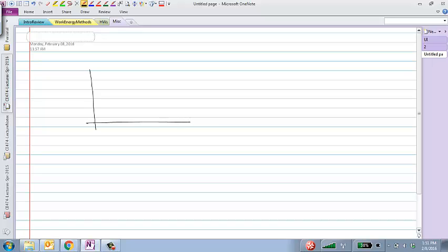So, a simple depiction of an elastic non-linear system. Let me first draw a linear elastic system. This is linear elastic, right? This is delta and this is P. You apply some load P, I get some delta. I apply 2P, I get 2 delta. On the other hand, a non-linear elastic structure would be something like this. The key thing about elasticity is that when you load it up this way, unloading also occurs along that same path. So as long as after removal of the load it comes back to zero, it's an elastic structure. But it's a non-linearly elastic structure in this particular blue curve.